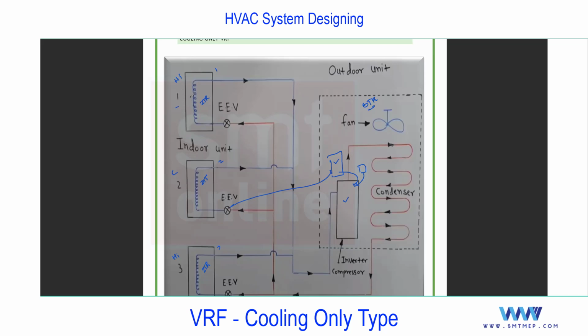And you know this, already discussed, right? You'll find the thermistors and you'll find a bulb at the evaporator side. That same example at the time of window AC. So you know all these units control the compressor by what? By return air temperature. For some time the return air temperature is the same as what you set. For example, in room 1 I set say 23 degrees centigrade. After some time the return is also 23. So this sensor, nothing but the thermistor, that bulb, will continuously monitor the return air temperature and give the signal